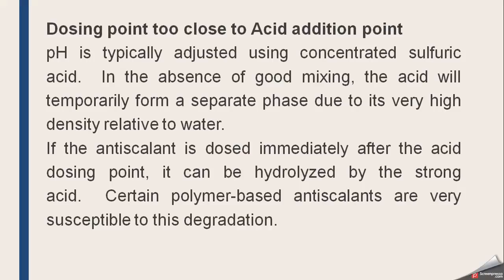If the sulfuric acid is not properly mixed, it will affect the antiscalant. That is, the acid will temporarily form a separate phase due to its very high density relative to water. So if we add the antiscalant very close to the acid, the acid can hydrolyze the antiscalant because it has a strong acid nature.